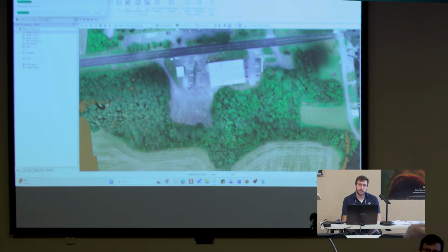So we're basically just making a shapefile grid based on our LAS data set, and we're going to use that to cut up our ortho. This should just take a second. Just let me know if you have any questions as we go along. Part of the reason this is taking some time is because it's looking at the LAS data and trying to clip to that. If you had that unchecked, this would be pretty much instantaneous. So just keep that in mind.